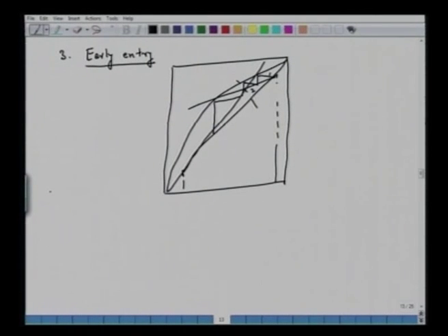Okay. So let's make a point here: suppose you have a new distillation column which you want to design, then there are three possibilities of locating this feed, at what feed tray we should have the entry. In one case, even before this Q line, one can switch down to operating line number 2 for the stripping column. In one case, we can have the early entry. We start from drawing the stages.